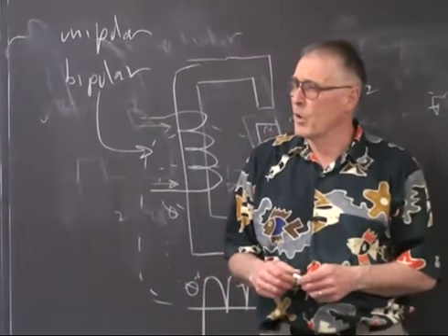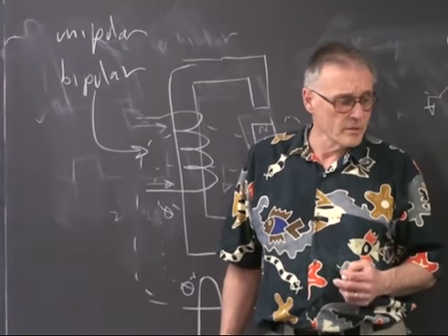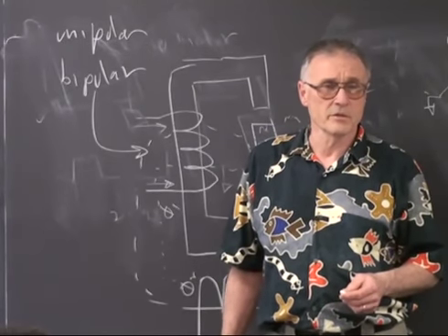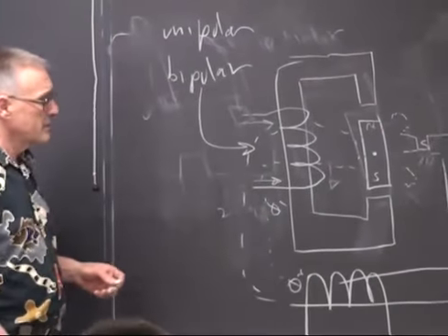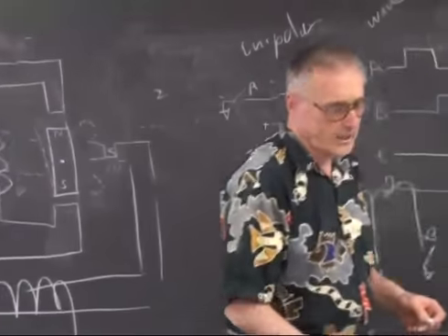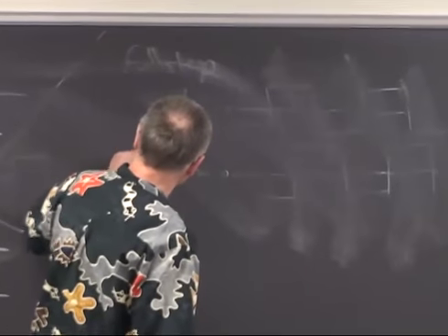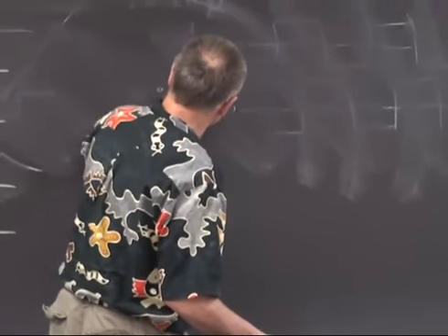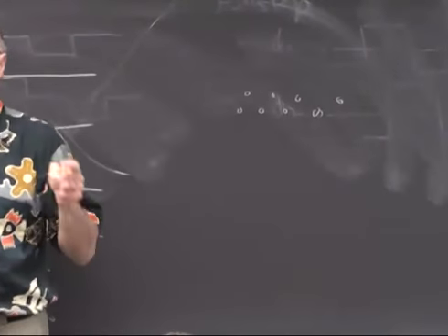I think an LM18200 is an H bridge that's appropriate. The only problem with the 18200 is that the pinout, it's in sort of a package that looks like a gigantic TO220, but the pinout looks like this, with a 1/10 inch spacing between each one of these, which means there's no way you can fit it into a whiteboard or any other board that we have. So that's kind of tedious.